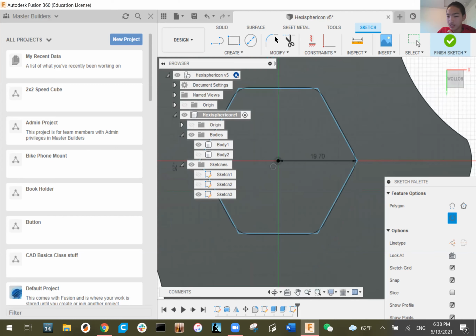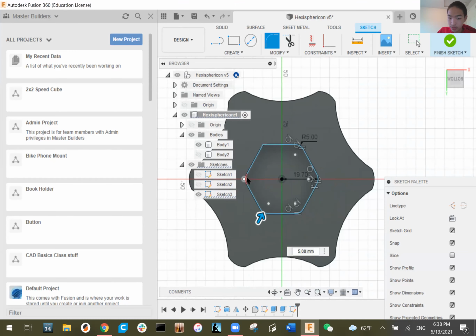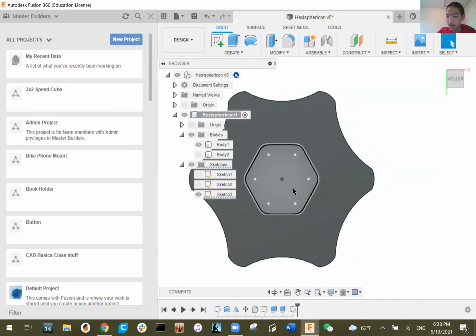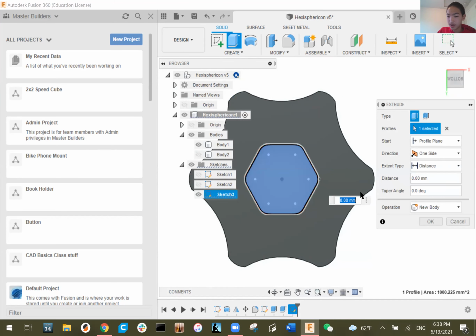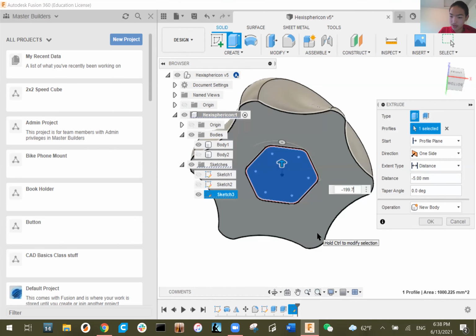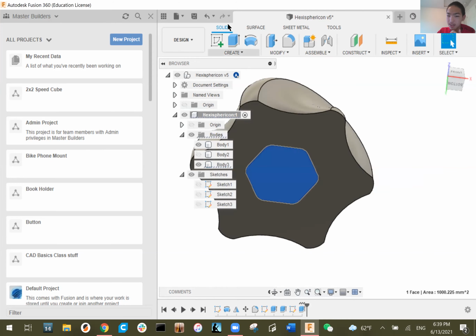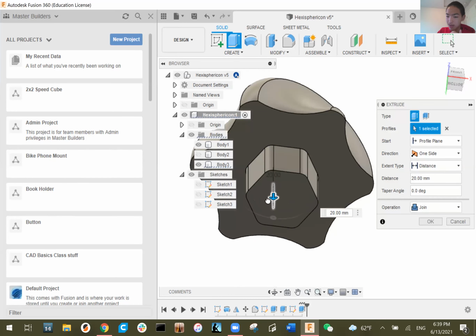Then what we do next is we again fillet this hexagon, by 5 again, and we do it for all sides. And then we've drawn the sketch for the inner object. Now we can extrude it 20, or we can extrude it by -19.7 to create an internal hexagon piece. That way we have something to connect both halves with.